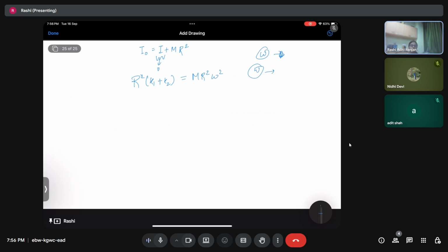if I want my system to be designed in such a way that x, here we have only x, is equal to 0, what I can do is choose the spring stiffness k1 and k2. Because when you look into the disk, it is difficult for us because we will need to manufacture the disk again and again, right? But if we choose the stiffnesses k1 and k2, I can change them. So for every value of omega, I can change the value of k1 and k2 such that this condition is always satisfied.